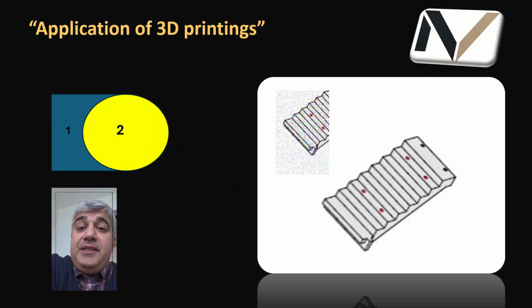For nearly 15 months now, our designers have been using 3D printing to produce architectural segments used during the mold preparation stage. One key challenge is that these printed elements must act as a reverse or negative of the final concrete shape. In simple terms, if the desired concrete outcome is 1-4, the 3D printed insert must be its inverse.